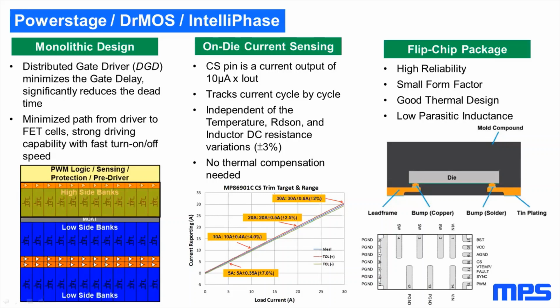The current sense accuracy is factory trimmed and almost independent of temperature, voltage, and the inductor parameter. So it is not dependent on the inductance or the ohmic resistance of the inductor. This makes your work much easier, as you don't need to always use a specific inductor which has a certain inductance and ohmic resistance. You also don't have to design a temperature compensated RC network across the inductor to create a small inductor current proportional voltage. And this voltage is quite often noise sensitive and critical to design.